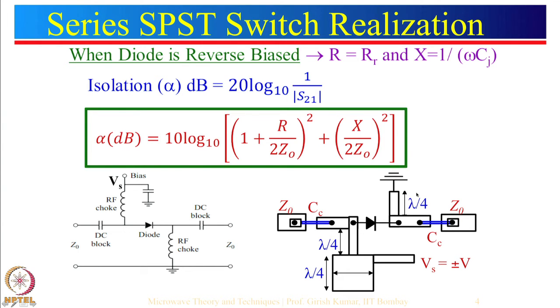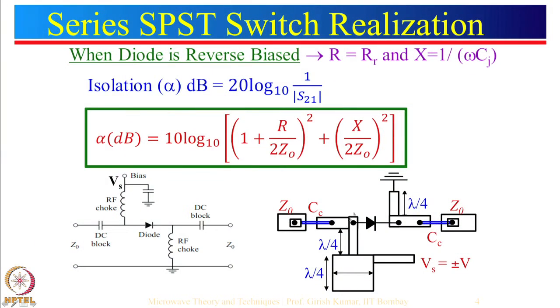But for many applications, for example, if you are designing something for, let's say, Wi-Fi, okay, Wi-Fi has a bandwidth of only about 4%. So this particular configuration will be very suitable. Similarly, if you are designing for, let's say, GSM 900, again at GSM 900, bandwidth is just about 7 to 8%. So this type of configuration is very suitable for narrow band applications, and you can see that component cost is very small in this particular case here.